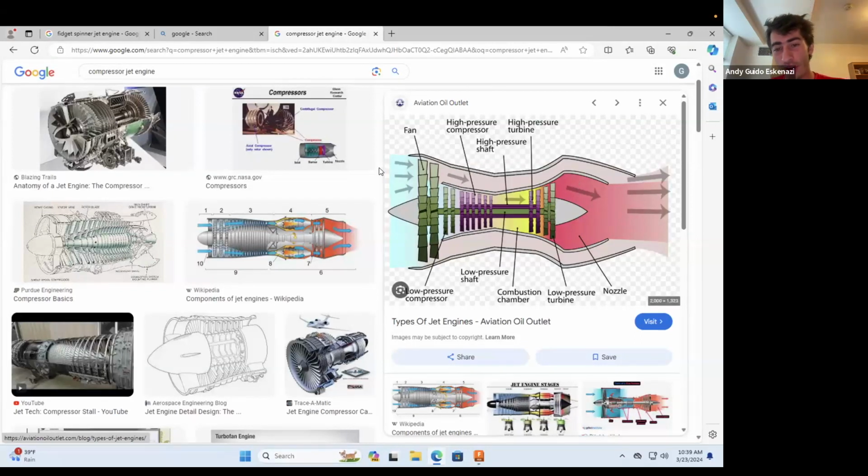So essentially, air is going to be flowing. If you fly an airplane, obviously you have these guys that power your airplane, and most of the air is going to be flowing through these streams that are called the bypass. And there's a bypass ratio, right? That determines how much air is going through these streams as opposed to the core. And it's the air that goes through these streams over here that actually provides the thrust that moves the airplanes forward. So then you might be wondering how do you make this thing, which is called the fan, move in the first place? And here they put like 2-stage fans, which is kind of weird. I haven't seen that in the past.